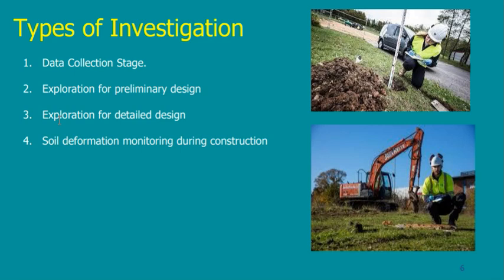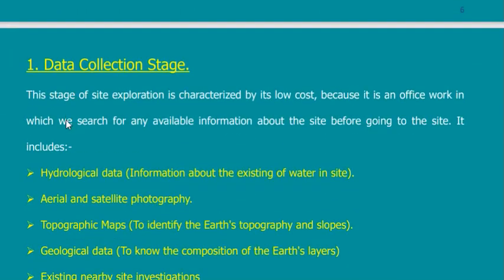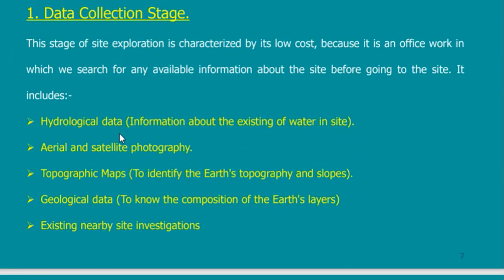I collected data, but I collected data for a reason. I need to give the structural engineer the bearing capacity of the soil. So to get the bearing capacity of the soil, you need to take the data, put it in some equations, make some calculations, and end up with what you need. So these are the steps for my investigation.